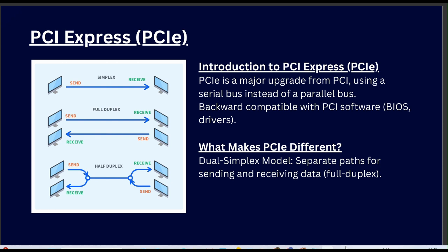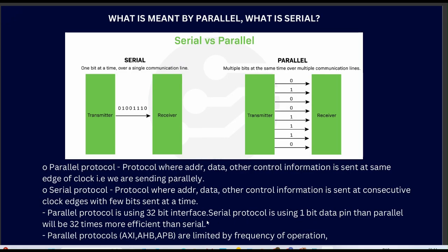And what were the disadvantages of the PCI protocol? Bandwidth limitations. Yes. So it has slower speed, high pin count, and significant issues when trying to push for faster speeds, because it is a parallel protocol, and we just learned that parallel protocols are limited by frequency of operation. We will understand what this frequency of operation actually means in our coming slides.